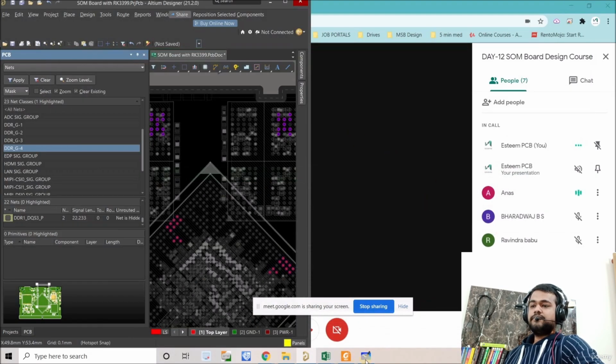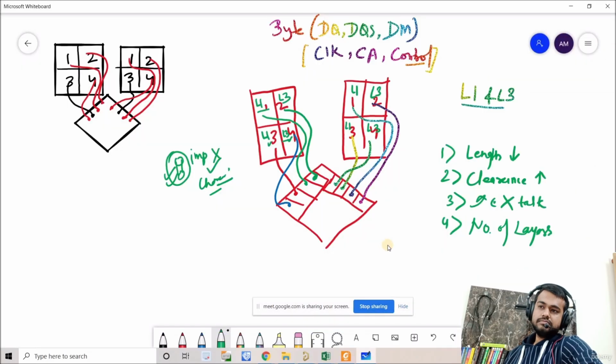Okay, thank you. Sorry, another question: is it better to set this rule in Altium, for example, the maximum skew? I think it's better to set skew properties or whatever timing rules are given. Whether you can verify that during the design with the Altium tool, I don't know. But if you have models, I will show you how you can verify those.